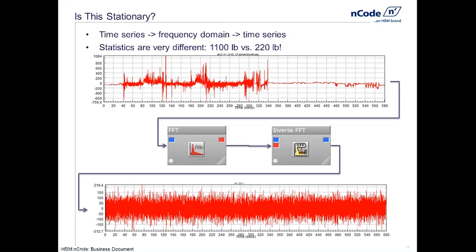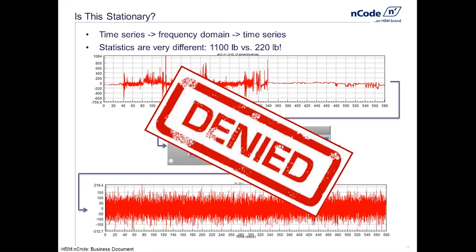right? So our two choices, we kind of have two bookends in our frequency spectrum, either what's the average amplitude or what's the worst case amplitude. And very rarely with transient data is it true that the transient stuff keeps happening with the exact same peak amplitudes. And also with transient data, we can't say that the average amplitude makes sense. So this is where things start to fall apart. When we have transient data, this concept of understanding data in the frequency domain starts to become tenuous. So in this case, I would say this is not a good thing, denied.